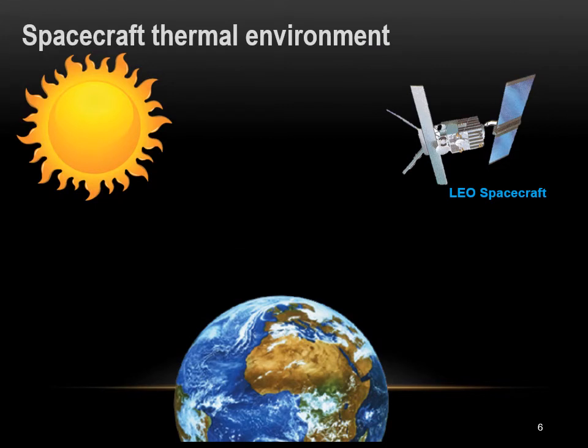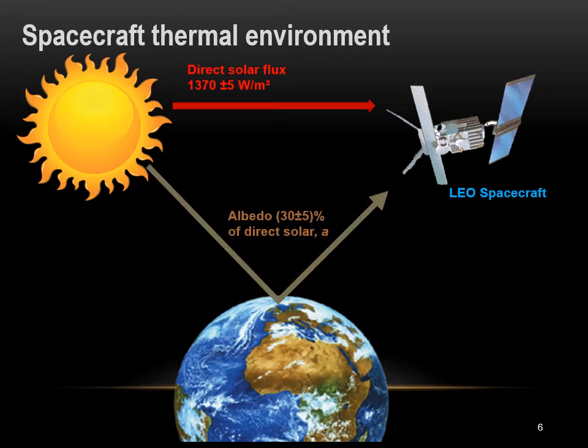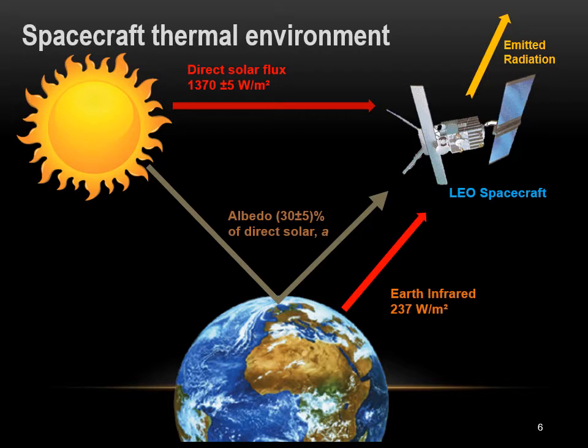Today we are going to learn about the spacecraft thermal environment. Typically, the biggest problem for spacecraft thermal control is removing heat. For the most part, we must maintain temperature inside even unmanned spacecraft at normal room temperature, which is 20 degree. In some cases, specific payload may have more demanding requirement. Infrared sensor, for example, require refrigeration unit to supercool them to minus 193 degree.